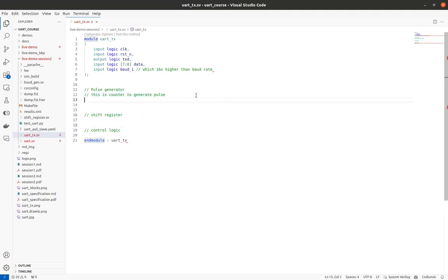Our aim is to implement a module and test it. We will load data in with whatever value we want, and make sure the busy and done signals work properly. Once we load, our data should be transmitted on the txd port.